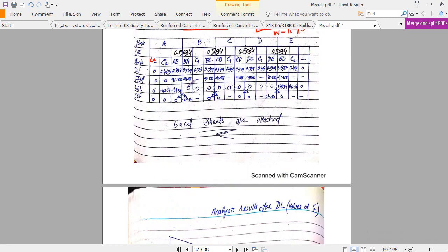And balancing now, this is important. What we have done here is sum these three values and multiply them with this distribution factor. From the addition of these three values you get 91.88, multiply with this distribution factor, you get this one. But you have to change the sign. Clear? You have to change the sign. And then you multiply this moment with this distribution factor, change the sign, you get this one.